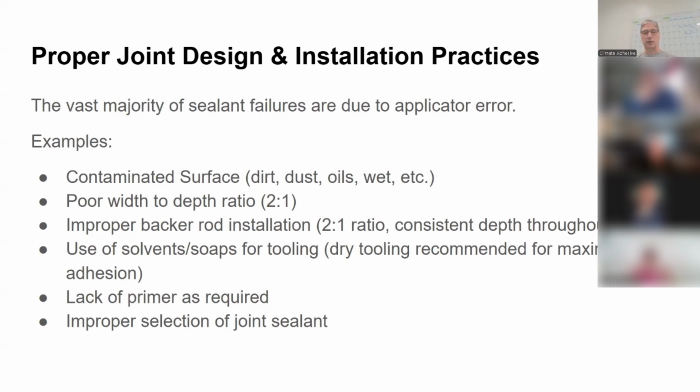Examples are contaminated surfaces. We want a clean surface to seal to. Dust is your enemy, dirt, oils. We don't want standing water. The ideal is a clean, fairly dry surface. For us, we're compatible with damp surfaces, so that's not as big a deal, but we don't want standing water on them. We don't want frost on them, things of that nature.